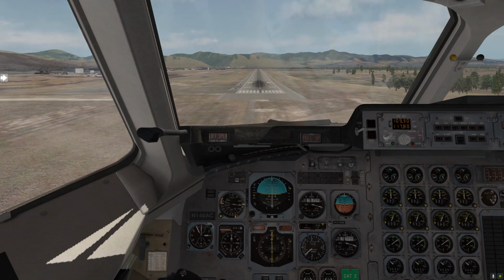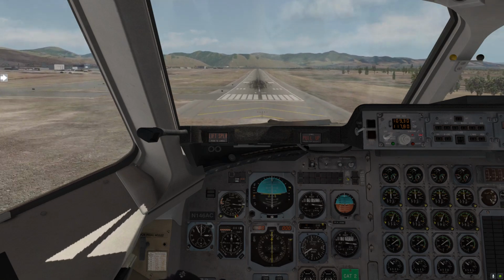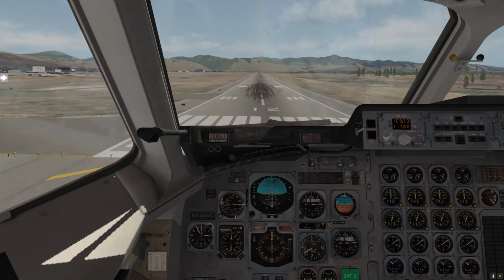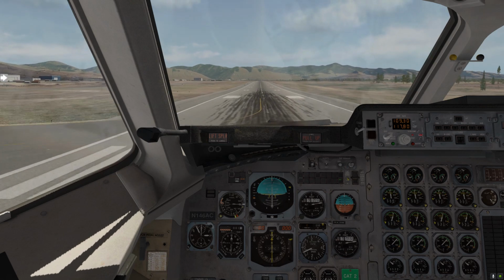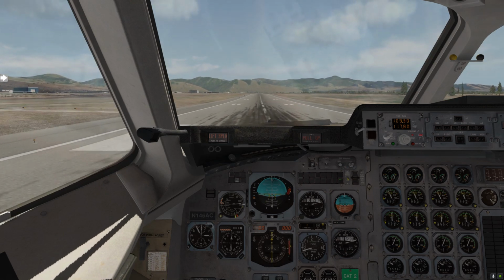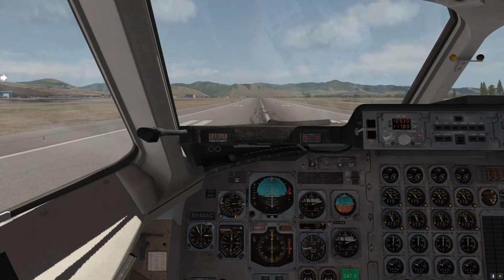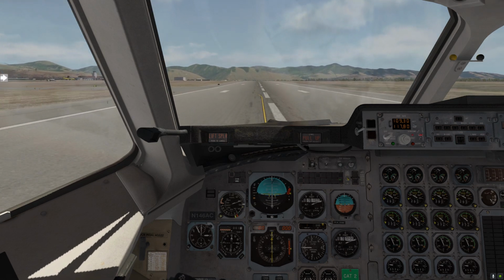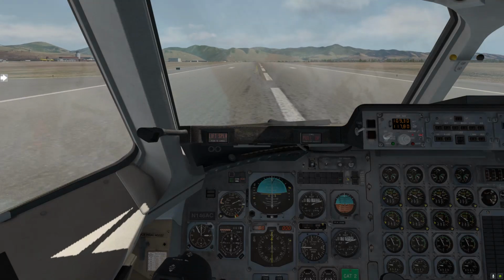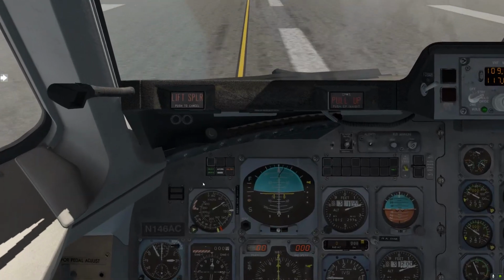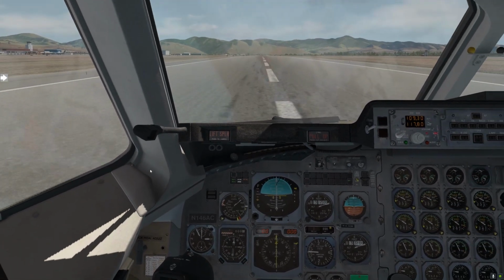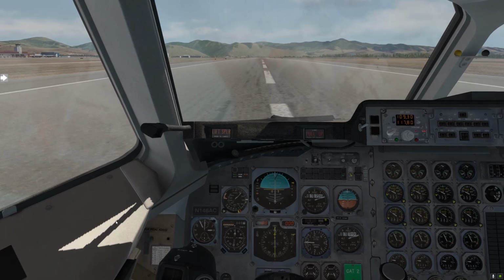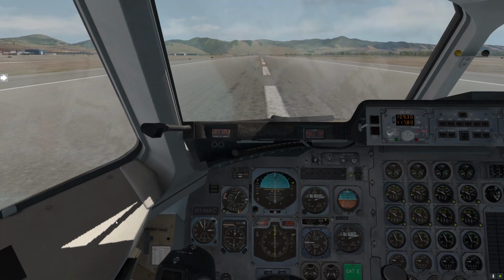Whoops, I kind of ducked below the glide slope there. That's okay. So as we come next to the runway, we're just smoothly going to pull the power to idle and smoothly raise the nose up about 5 degrees and just gently bonk. There it is. So now I can press the speed brake button again as I let the nose down. That's going to deploy the spoilers. So we have spoilers deployed and air brake deployed. And then just smoothly on the brakes, and we'll take this exit.